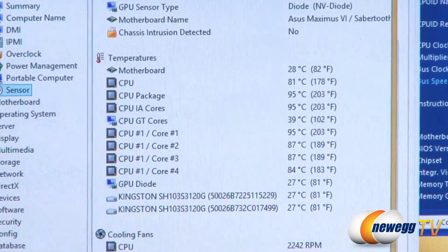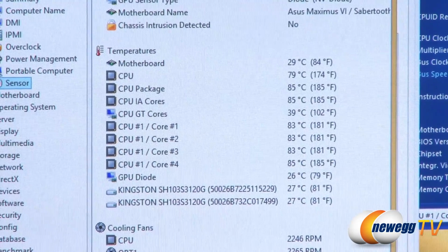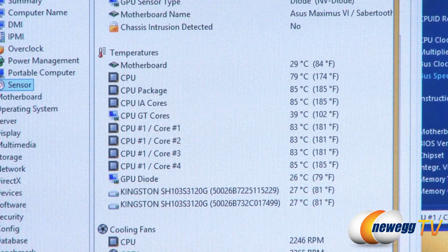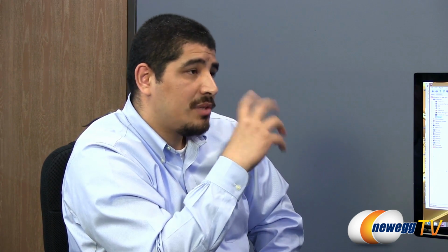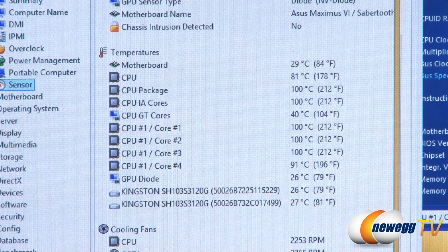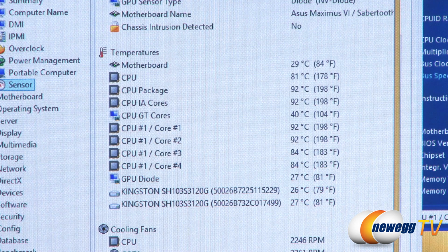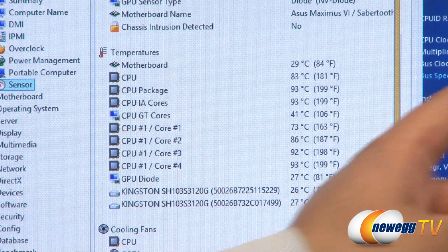These are going to jump up and down quite a bit because of the internal design of the CPU platform and the fact that the DTS sensors are not designed for accurate thermal detection, but to monitor throttling. There's a very big difference between accurate temperature monitoring and monitoring for throttling, so there's going to be variance. Plus, because the CPU is executing other functions such as switching frequency for the internal IVR and other variables, these numbers are going to jump up and down, to fairly large deltas. Because of that, you need to compensate with a good thermal solution.